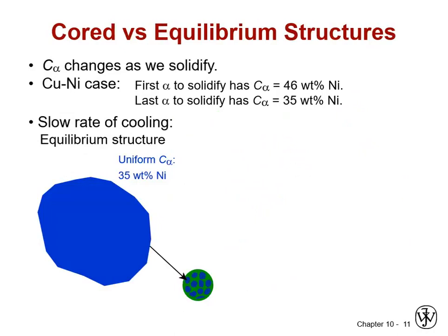Okay. We mentioned that phase diagrams only apply if we cool slowly and keep everything at equilibrium. We're going to take a look at what happens if we cool too fast. And in this case, too fast literally refers to whether or not diffusion in the solid can keep up with the rate of deposition of new material from the liquid, and what will happen if it doesn't. So in this case, cooling at equilibrium has a very specific definition in reference to a mass transport property that we've already studied, namely solid state diffusion. So this is kind of back to that Fickian diffusion concept.